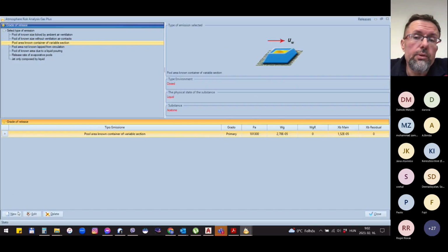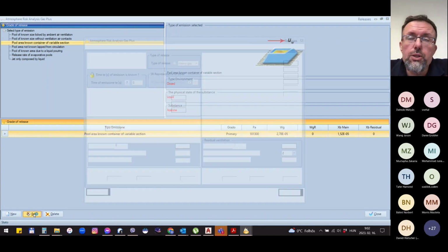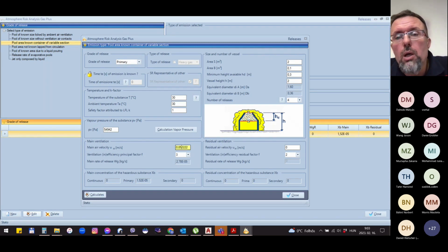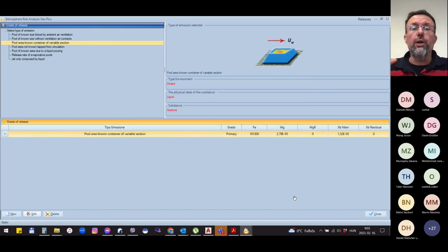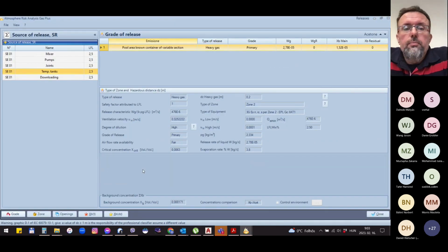So that's very important. The temperature class of the installation, the minimum requirement I'm talking about, shall always be related to the substance in the environment, okay? And when we have multiple substances, certainly you have to go straight forward to the more dangerous one, okay?